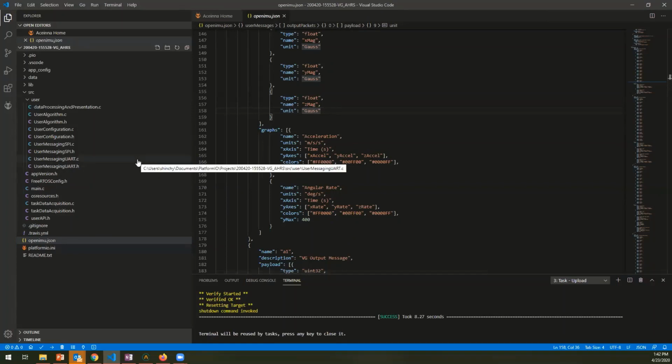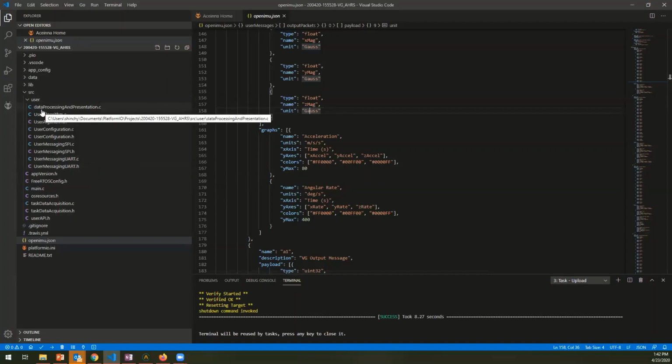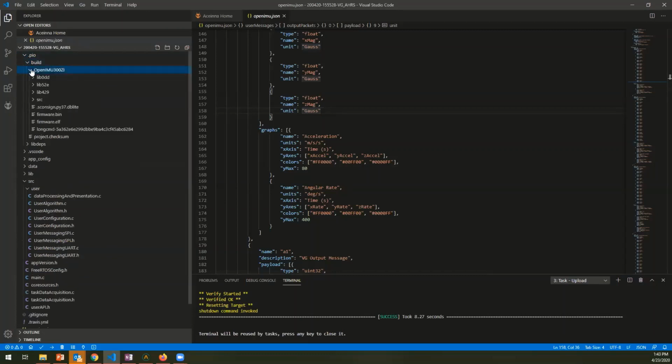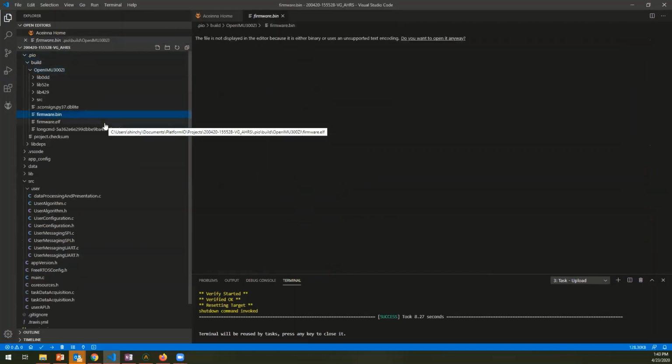One final section to point out is when we clicked the build button earlier and built this application, the binary itself can be found at the following location under .pio/build, and it's this file here, firmware.bin. You could save this and use the ST-tools to write this to the part directly. And this is basically the same binary that is available in Navigation Studio in the code section.